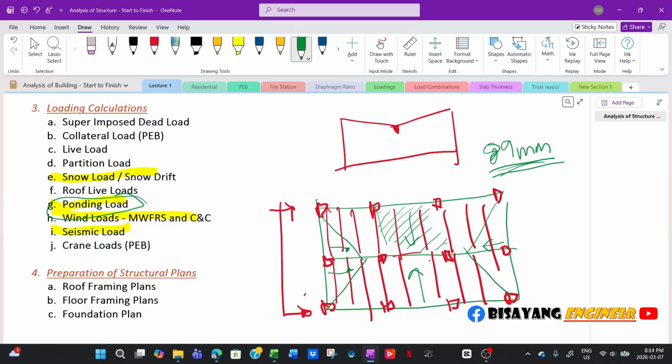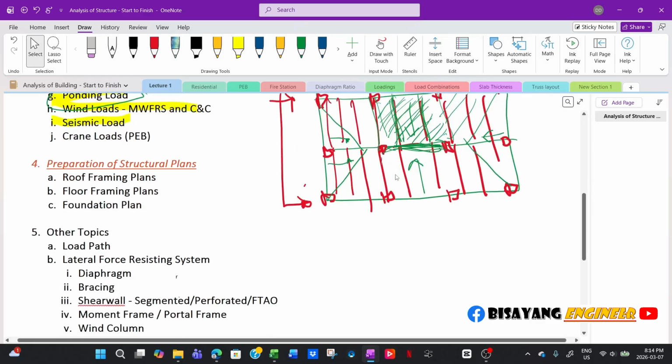So once you have this information, calculate the area. Once you calculate the area, you have the volume. Now that volume will cause a deflection of your beam, right? Every time it causes deflection, the volume will accumulate, and then you will have a larger volume. The total volume of water will increase until it reaches the maximum deflection, the actual deflection. But in that book, the solution is quite simple and really practical.